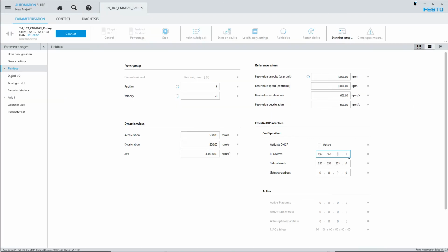You have to come in here and do the exact same setting you have already previously set through the software. Otherwise, when you download it and then you do a reboot, it'll come back with whatever this IP address is here, which is the default, and that's the same default as the programming port up top here, and then you'll have a conflict and you'll be pulling your hair out, okay?